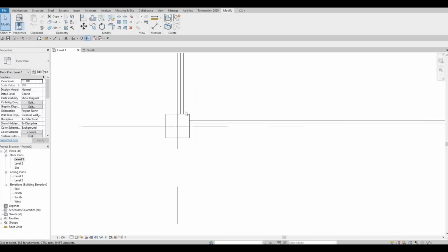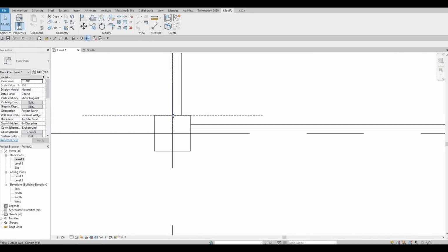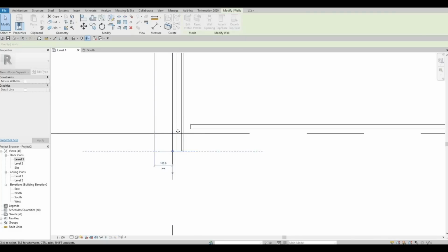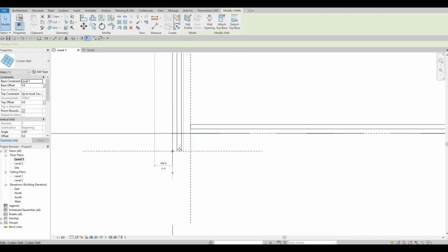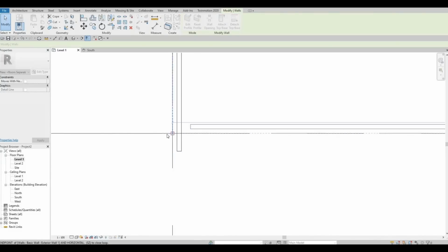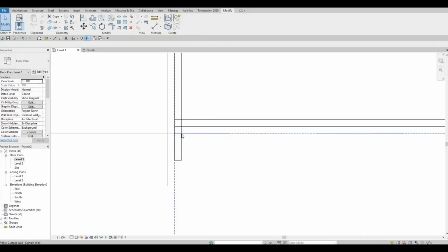And then once we do that, as you can see, we need to zoom in and remove the remaining walls like that. So that's what I did. Then now we could just extend this a little bit. And we could use AL, that's Align. So we just need to click on Tab and then select this one. As you can see, it moves like that.